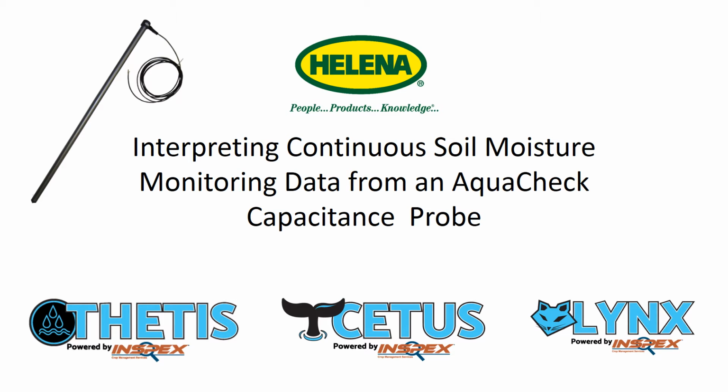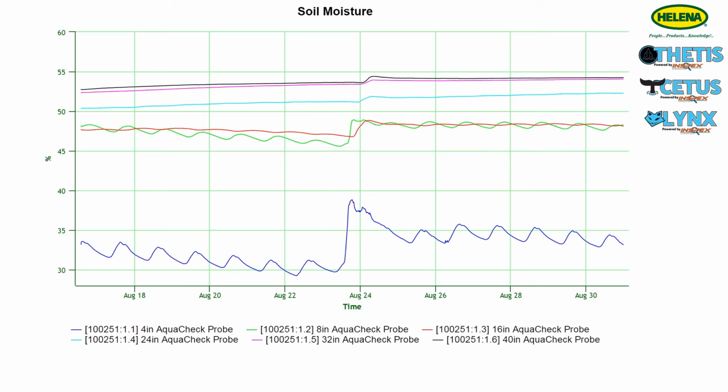This video shows typical continuous soil moisture monitoring data from a capacitance soil moisture probe and briefly describes some considerations in the interpretation of the data. The data shown here come from an AquaCheck capacitance soil moisture probe with sensors configured to read relative soil moisture at 4, 8, 16, 24, 32, and 40 inches below the surface.